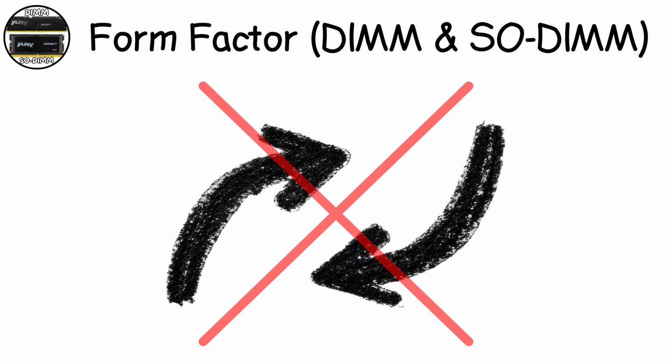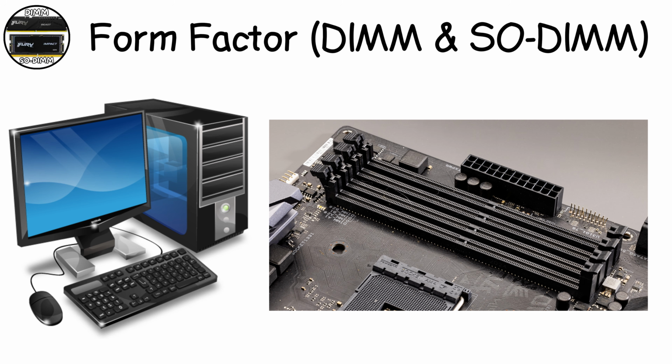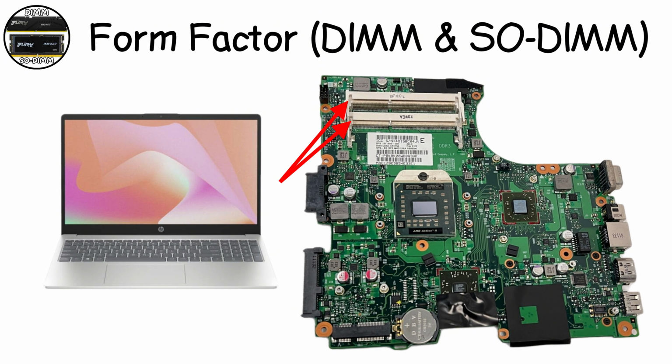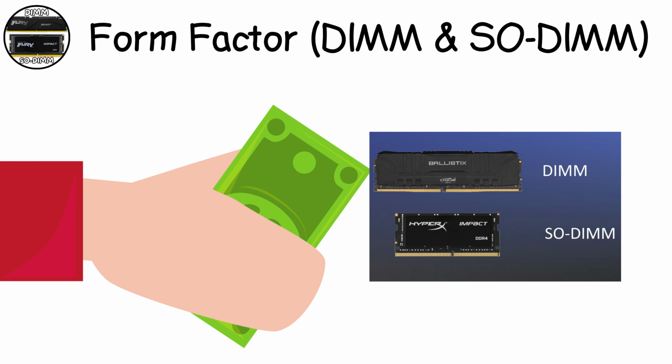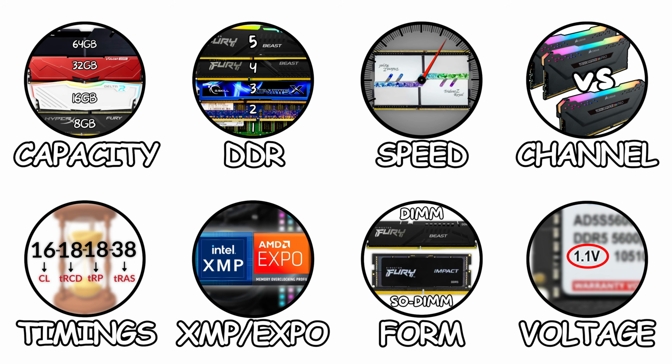These are not interchangeable. Desktop motherboards have DIMM slots. Laptop motherboards have SO-DIMM slots. When buying RAM, make sure you're getting the correct form factor for your system.